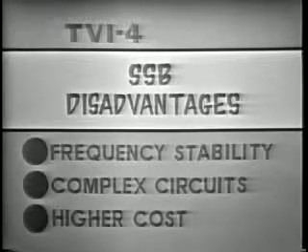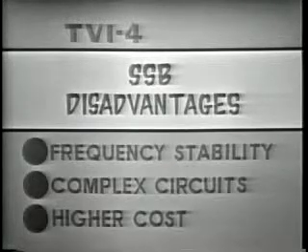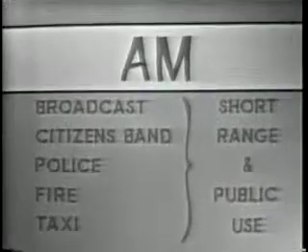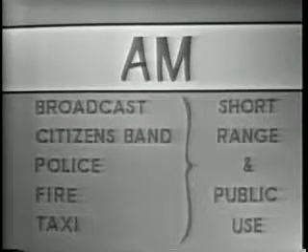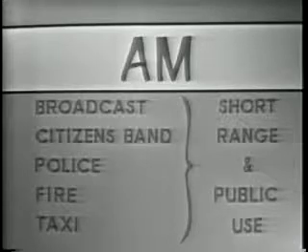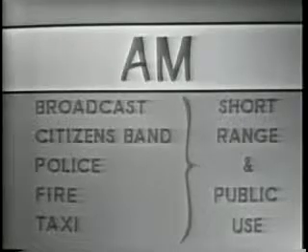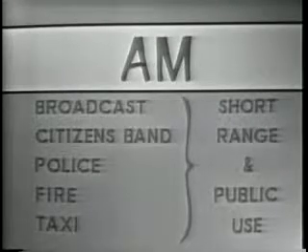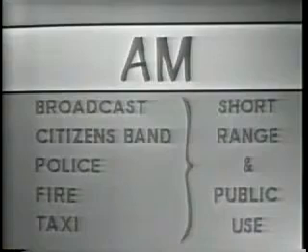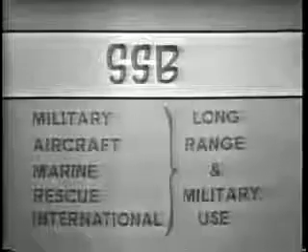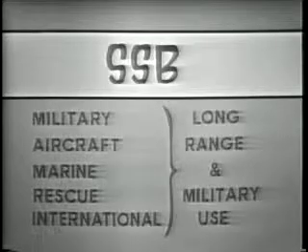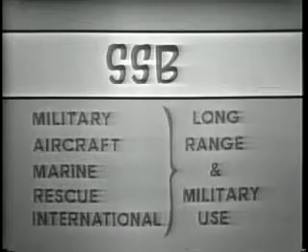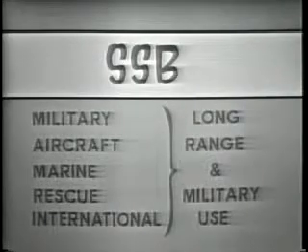But let's compare the practical application of conventional AM and single sideband. For short-range communications for the general public, it would be impractical to have all of the public trade in their AM equipment for perhaps more expensive single sideband equipment, which might require more skill in tuning and higher maintenance costs. So conventional AM will be with us for quite some time in many applications. But for uses requiring long-range communications in ever-increasingly crowded frequency bands, the operational advantages of single sideband far exceed its possible increased cost.